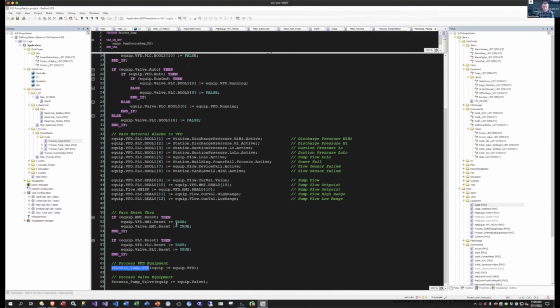And inside that VFD code, I determine whether the VFD is ready or not, and actually send it a run command or not, based on that VFD. Same with the valve. The valve gets a variable that I set to tell it to either open or close. And then I call a process POU for that valve to handle it. So everything's structured. We're calling these programs and passing values as VAR_IN_OUTs, and handling those. I hope I've explained that part well.